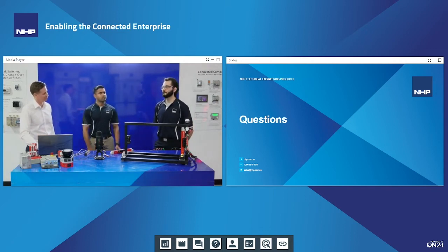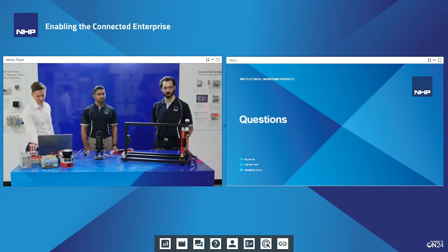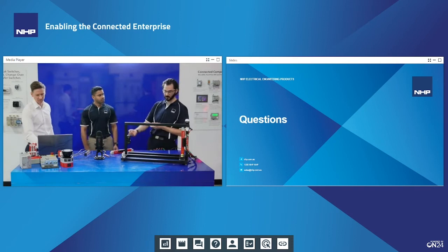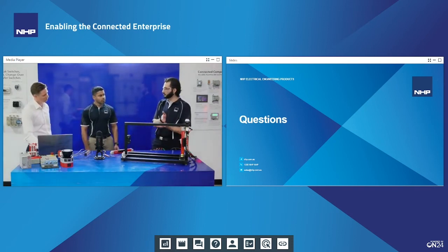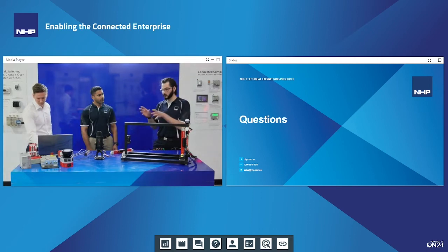Well, that's actually not a bad question though. As far as loading is concerned, depending on your controller, there'll be a certain number of Ethernet nodes that you can add to it. So you treat a SIP safety device as you would any other SIP device. It consumes a connection. So if you're using a fairly low-end CompactGuardLogix, there'll be a limited number of connections that you can have. So your SIP safety network has to be smaller, or you might segment it to have certain sections of your machine operating with their own dedicated GuardLogix controller.